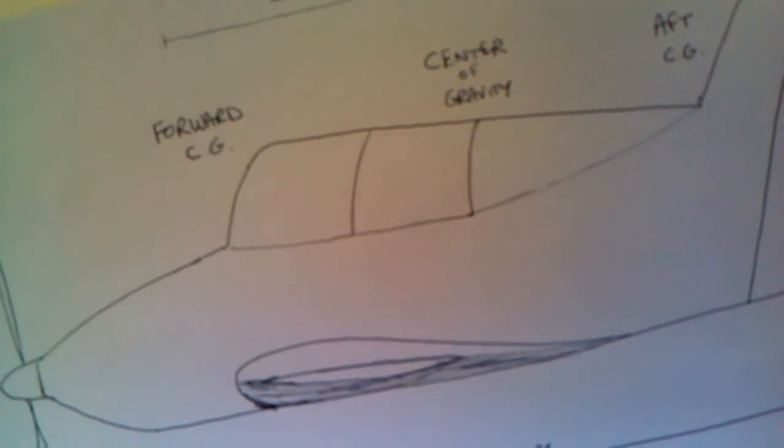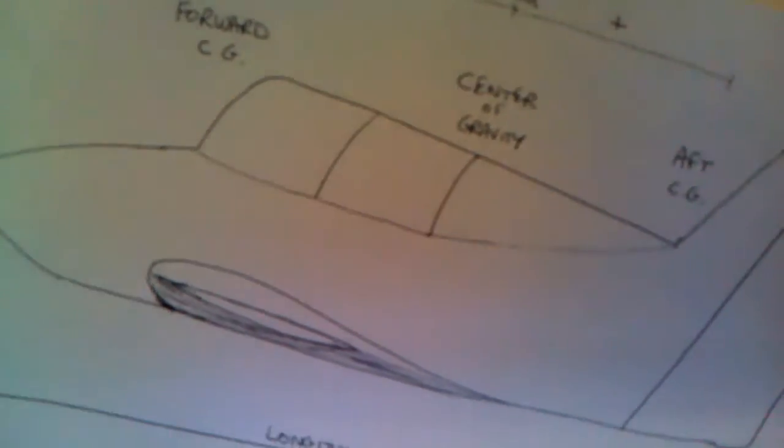Because of this, you're going to be flying at a higher angle of attack to overcome the weight of the people in the front. You load the airplane and it naturally wants to do this a little bit, so you're having to pull back on the tail like this and kind of fly through the air like that. So greater drag, which leads to less performance. But it does have increased stability because the weight's closer to that center of gravity. The exact opposite is an aft CG.